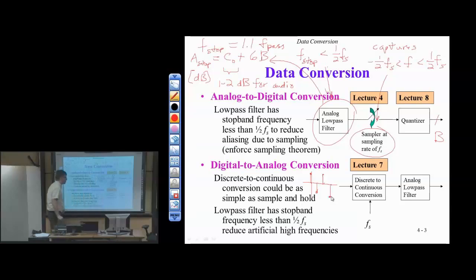So how about a nice alternating 1, -1, 1, -1, something like that. We'd love to have this, in the end, look something like a sinusoid, if we could. If everything were ideal and perfect, we'd have a really nice looking cosine that comes out. This we'd love to have come out. In practice, we'll have noise, and we have all kinds of things. So in practice, we have some work to do. This is discrete time in the time domain, and we also have quantization in the amplitude.